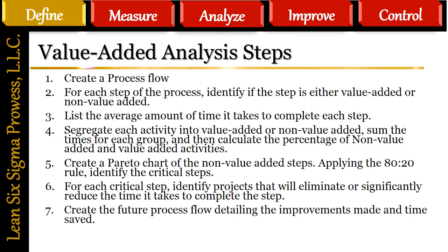The time it takes to complete a task can vary greatly depending on who is completing the step. If this is the case in point, use the average amount of time. During the observation exercise, for each operator observed, write down the time it takes to complete the task as well as the name of the operator. After the observation, analyze the data for max and min times, noting steps with the greatest amount of variation. These steps should be areas marked for future improvement.